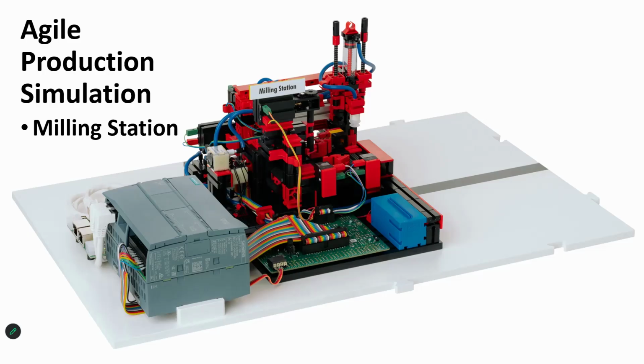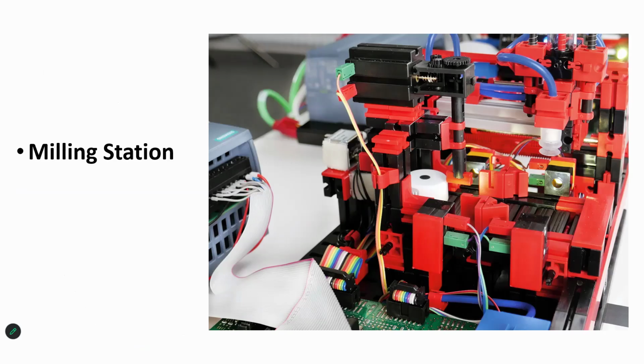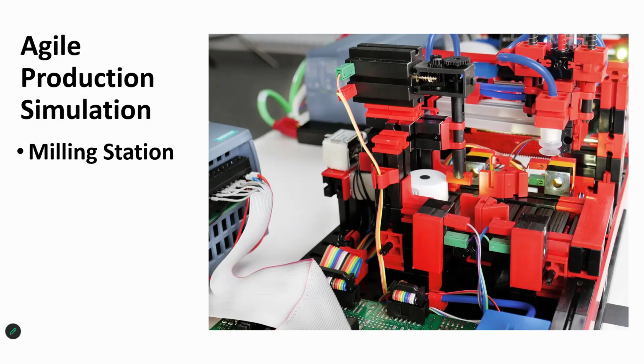We're going to, of course, touch on this again a little bit later in the presentation, but continuing along, much like we saw at the previous stops, the milling station, again, consists of a docking station for the AGV. And once again, once the AGV has docked at the station, a vacuum gripper at the milling station picks up the workpiece from the back of the AGV, and then puts it onto a conveyor belt located at this station, where the conveyor belt transports the workpiece under the milling machine.